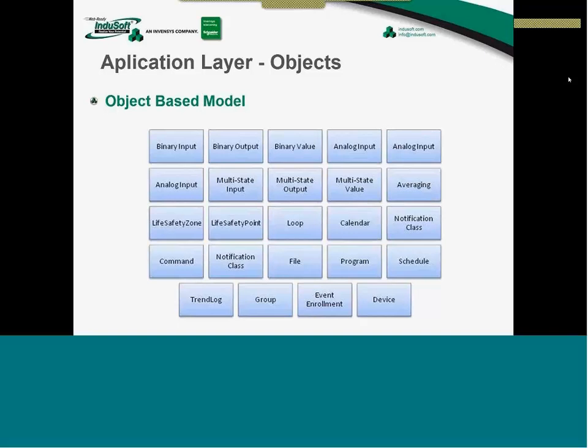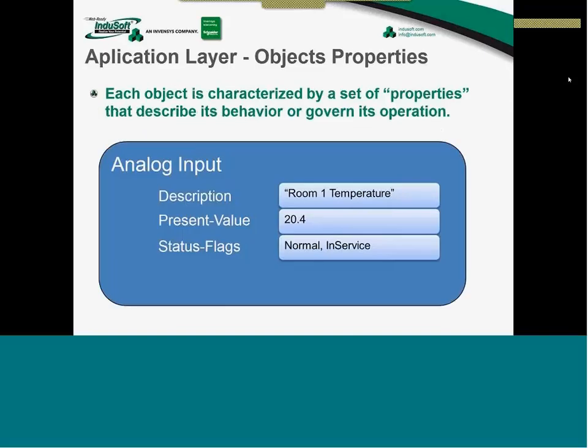Objects represent either physical or virtual information, such as analog and binary inputs, outputs, control algorithms, specific applications and calculations. This is an example of some objects. So each device is composed of a lot of objects, and inside each object we have a lot of properties. Each object has a collection of properties based on the function and purpose of the object.